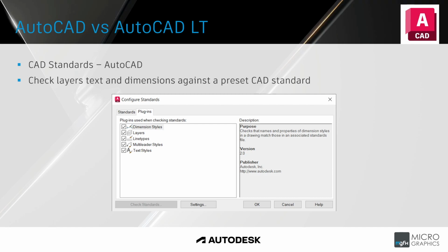So if you're the manager in the office, the CAD Office Manager, you can actually run what's called a DWS file. You've probably seen it if you go File, Save As, and if you just go to the DWG drop down, you'll see there in the middle is a DWT and a DWS. DWS is the standards file, and you can attach a standards file to your DWT template file, and it will check and give errors and warnings when you start deviating from your standards. Okay, so it's a nice check for when you are creating and sending out drawings like this over here.